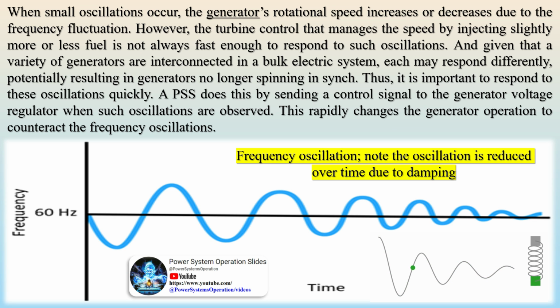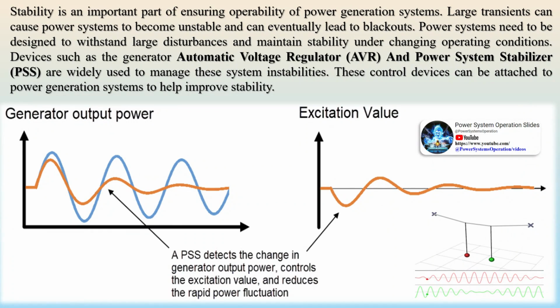In recent years, as interconnected power systems have become increasingly complex, the presence of poorly damped low-frequency inter-area oscillations has strained stability constraints and limited power transfer capacity. Therefore, adequately damping inter-area modes is crucial to secure system operation, ensure reliability, and generally increase power stability.